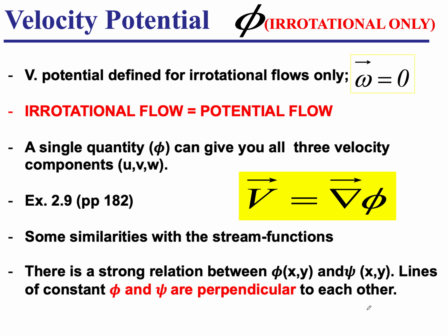So the first theory that we are going to consult is this potential flow theory. We're sort of ignoring the boundary layer. We're saying it doesn't exist, and it does exist, but we're going to solve for our flow field and for our pressures and velocities in the absence of a boundary layer. So if I have my velocity potential function, then I can derive my three velocity components, u, v, and w, which comes to be a very nice tool.